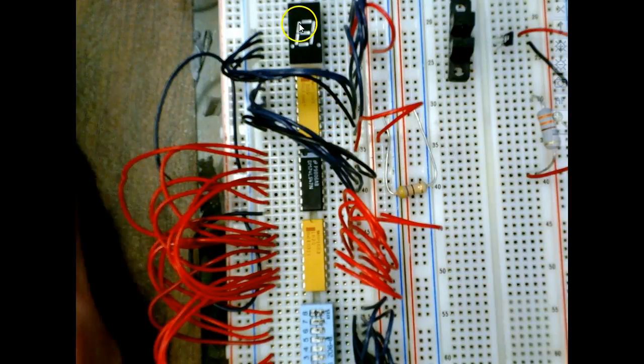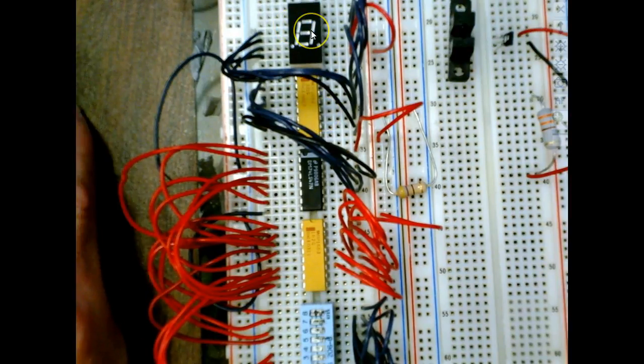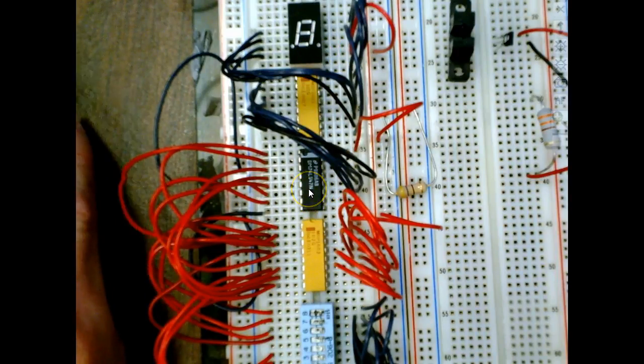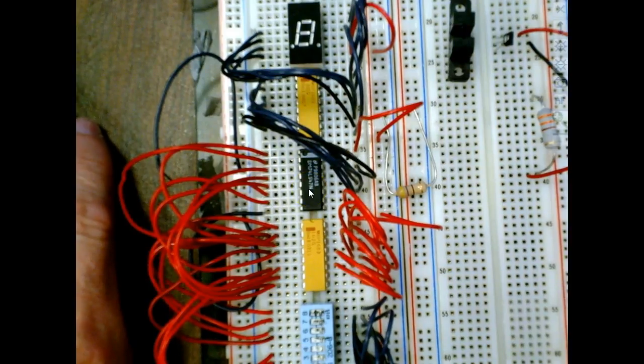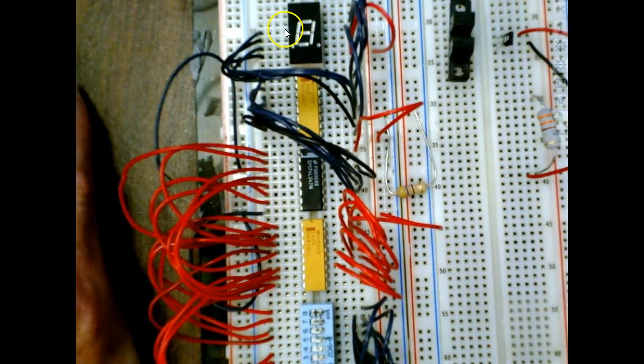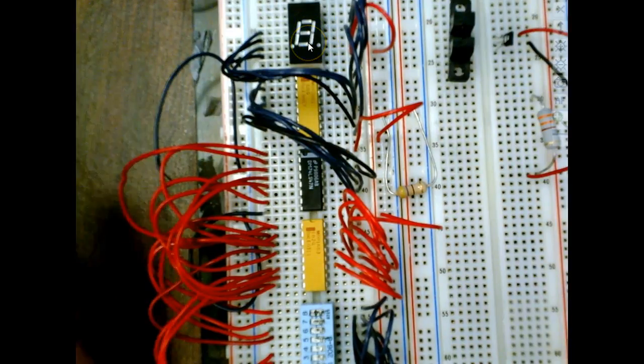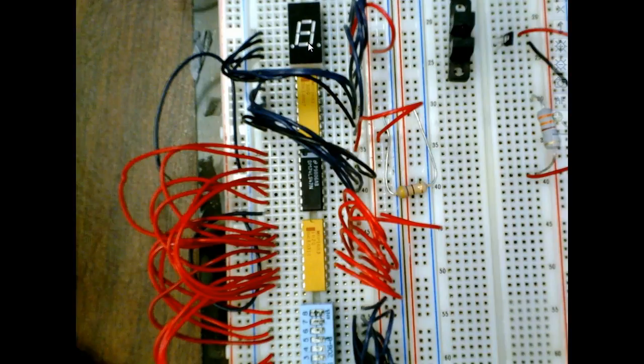So we're okay on a 7447. So what is a 7447? It's a decoder. And what do we call it? It's a binary to 7 segment. And what does it do? It does a common anode display. A 7448, what do you think that does? It's a decoder, but just think, what do you think a 7448 does? It's a common cathode. So 7447 is a common anode.